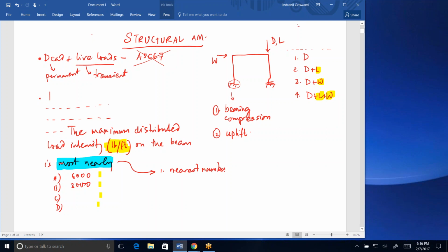A good example might be they say that the ADT on a particular bridge in the year 2000 was 35,000, and assuming a population growth of 3%, what would you project the ADT to be in 2020? We all wish we had a question like that. 15 seconds, but basically what you're doing is geometric growth according to population of the traffic.